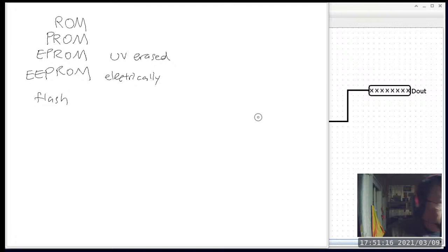With SSD, maybe, but it still depends on whether the bus lets it happen or not. Because a lot of times when you're reading from an SSD or anything that is high speed, you're using DMA, direct memory access, and DMA is a mechanism that is done by what we usually call a chipset, which is not really central to the core of a processor, but is a peripheral device that is very close to the processor.